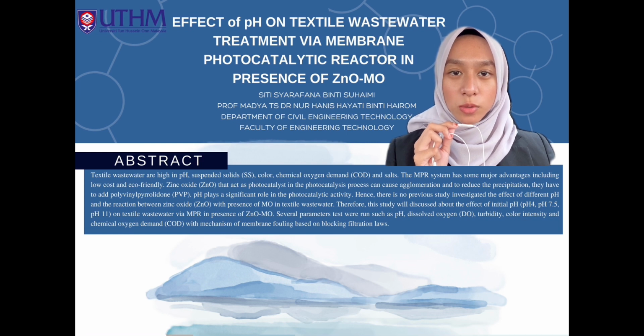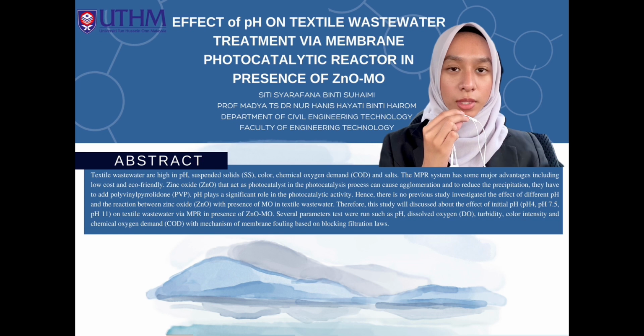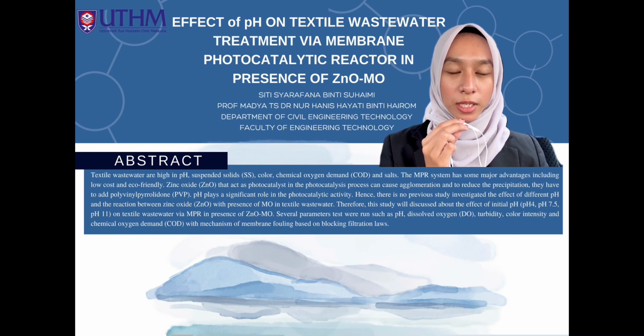Hence, there is no previous study investigating the effect of different initial pH and the reaction between ZnO with presence of MO in textile wastewater. Therefore, this study will discuss the effect of initial pH, pH 4, 7.5, 11 on textile wastewater via MPR in presence of ZnO-MO. Several parameters were tested: pH, DO, turbidity, color intensity and COD, with mechanism of membrane fouling based on blocking filtration law.